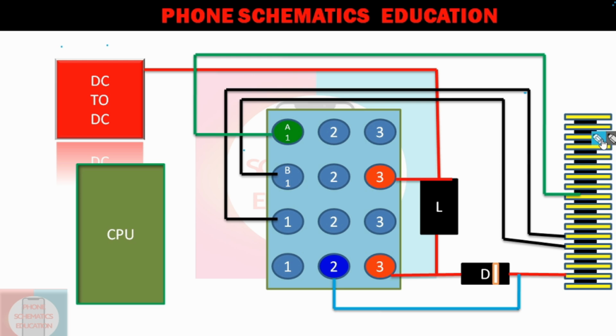Clear? So multimeter on DC mode. Now DC voltage. We check in forward bias with the red probe, black probe on ground. So check this line first, the anode line. Most probably after the cold testing you cleared this line, you get 3.7 to 4 volt if the fault remains the same.